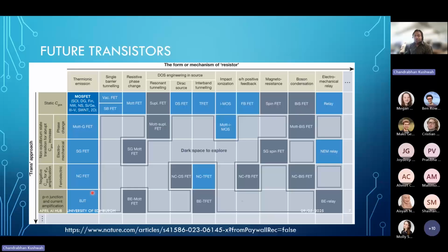through a PN junction. Now researchers are looking at re-engineering this control mechanism. Promising innovations include negative capacitance FETs, suspended gate FETs, and mod gated FETs. These devices experiment with new physics, like using ferroelectric materials to achieve a negative gate capacitance, or employing nano-electromechanical or phase change switches to rapidly boost current flow. These changes enable steeper switching characteristics, which is key for reducing power use.